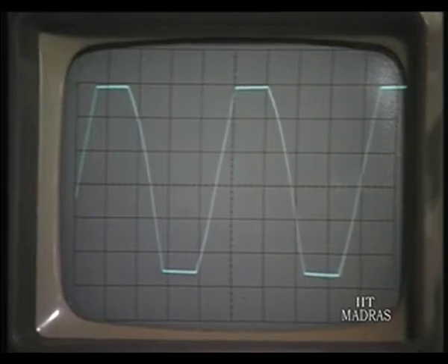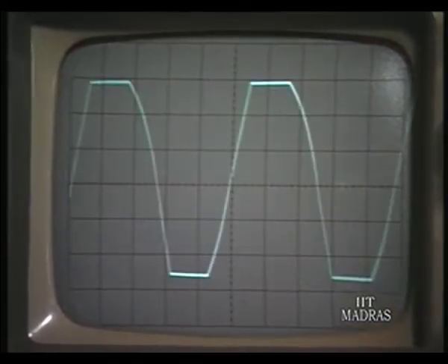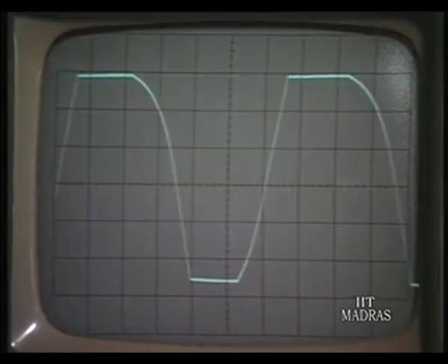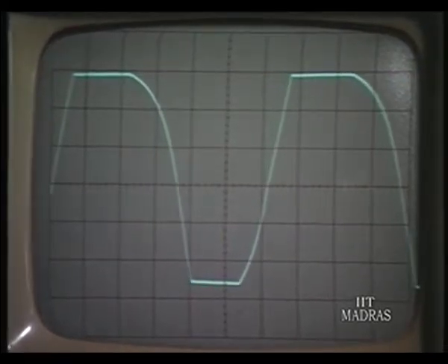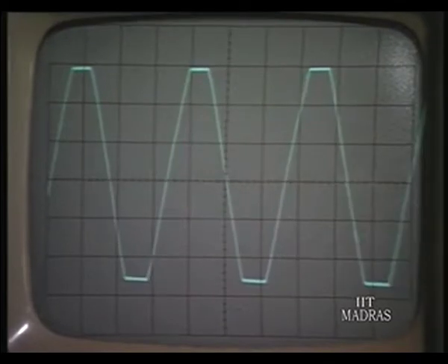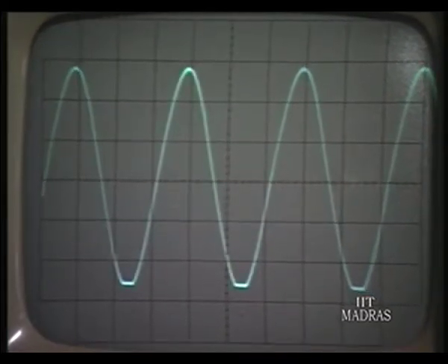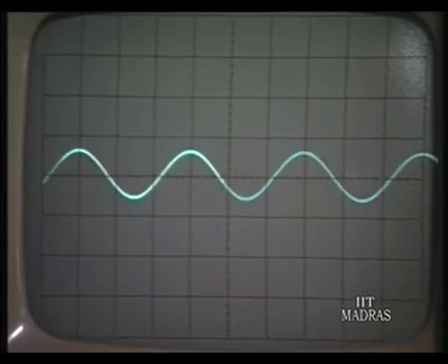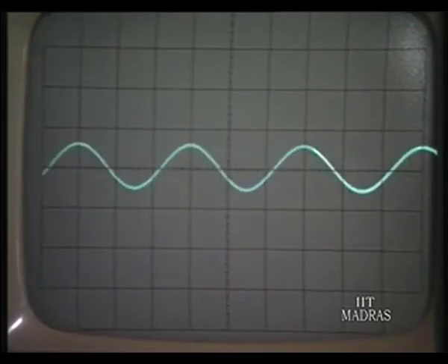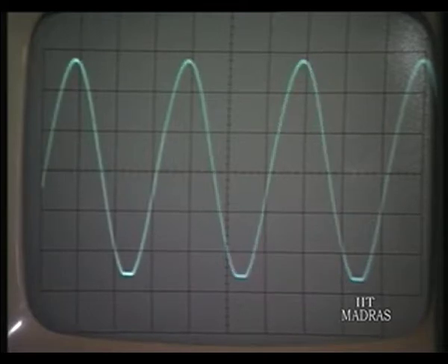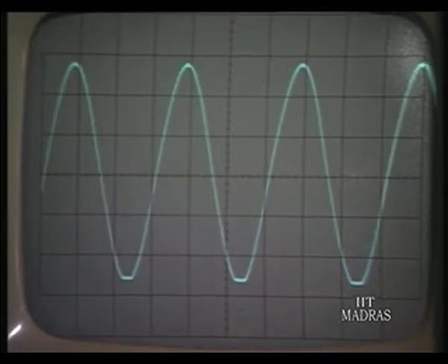See, it has gone almost up to plus minus. She has introduced too much positive feedback here. Now it has gone to saturation altogether. Too much of positive feedback. And this is clearly demonstrating the effect of too much of positive feedback. You have to introduce just enough positive feedback in order to get rid of the negative feedback. Then only it will give you a perfect sinusoid, otherwise it will be distorted.